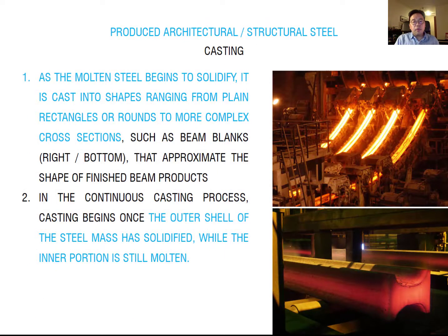So now you understand that after having the pure low carbon steel, we have to produce the architectural elements such as metal beams and columns. So how do we create the architectural elements? First, the fabrication method is casting. Steel casting is one option for making architectural metal products. You simply make a mold, a reusable mold, then you pour the pure metal into it, and you can make the desired shape. It is possible to make a very complex shape because it depends on the mold shape. Okay.